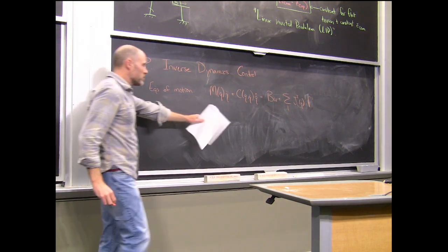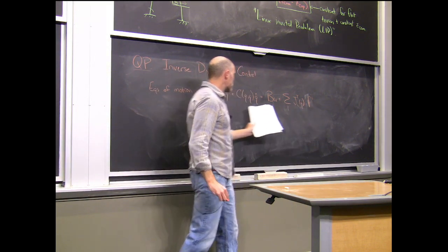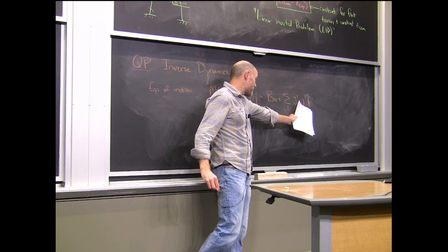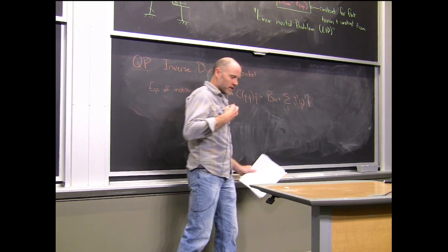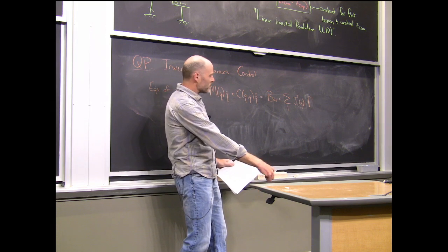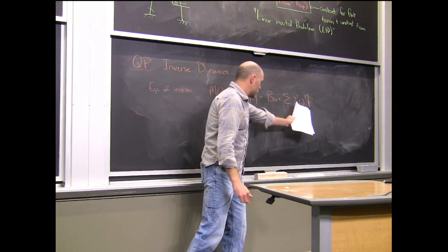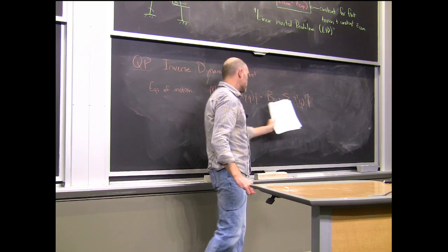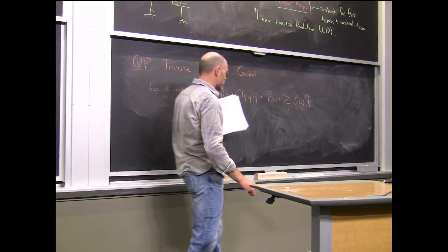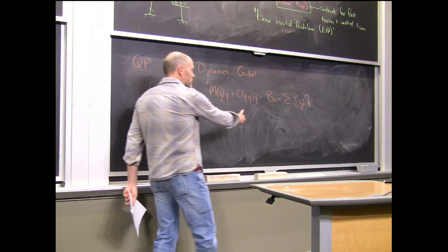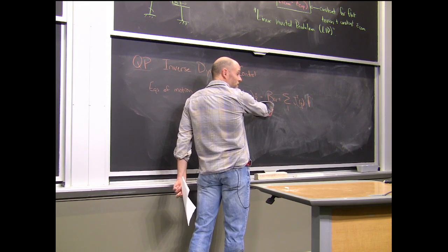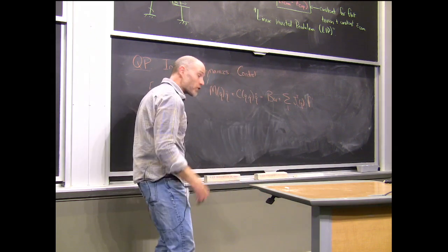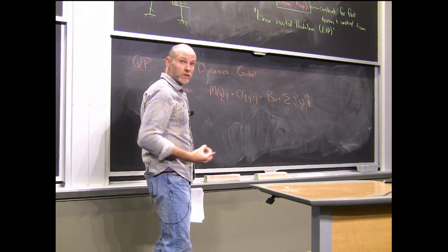What's interesting is that the way the forces enter the multibody equations is this particularly simple form. They come in a control affine, in an affine way. This is a Jacobian that is the gradient of basically the signed distance function that describes those forces, but it's the kinematics of where that force is located, which maps it into the joint torque coordinates. B might not be full rank, because Atlas is under-actuated with a floating base. All of its internal joints are actuated, but its floating base coordinates are not actuated.